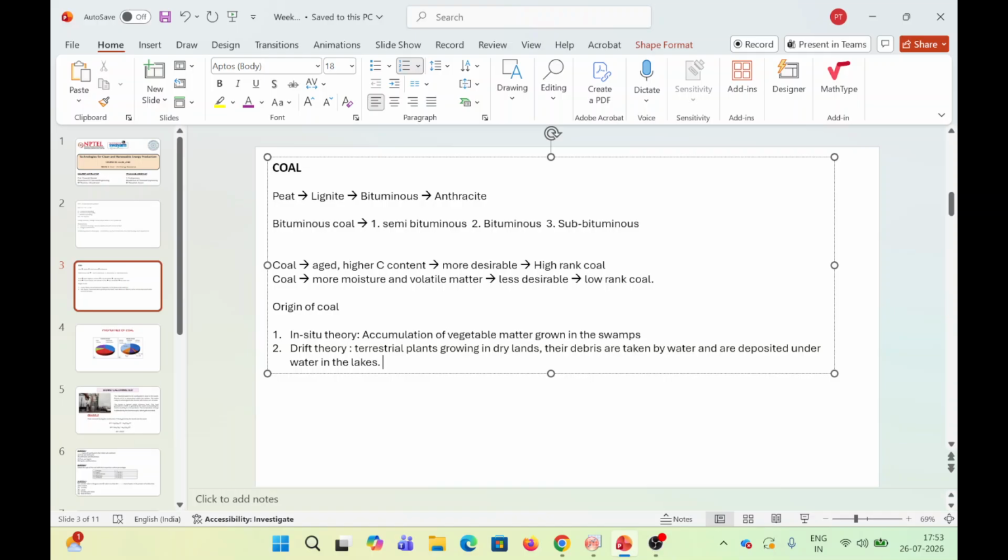But coal as such has a certain drawback. One of the major drawbacks is that the mechanical strength of the coal is not very appreciable. So it tends to break into powders or some sort of granules. When you want to use coal for furnace or oven applications, it is not a very suitable candidate, because its mechanical properties are very bad. So in order to improve upon the property, the coal is transformed into coke.